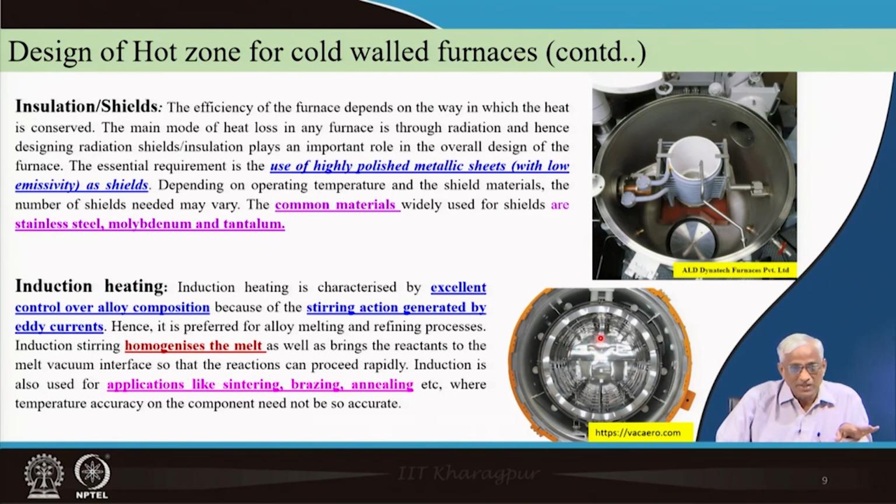For lack of time I cannot go into it, but later, if there is time in some other application, we will cover it. And highly polished surfaces have to be there, because emissivity should be as small as possible, so that the heating is totally given to that job. So, you have to know the heat transfer designs, not only the shielding, but also the thermal insulation outside, and the radiation heat transfer calculations have to be done.